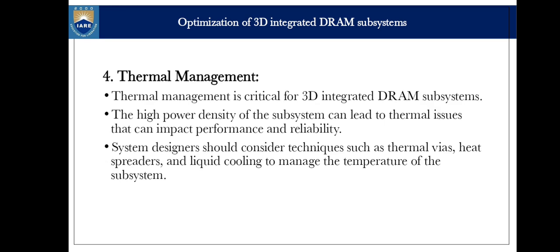Thermal management. Thermal management is critical for 3D integrated DRAM subsystems. The high power density of the subsystems can lead to thermal issues that can impact performance and reliability. Subsystem designers should consider techniques such as thermal vias, heat spreaders, and liquid cooling to manage the temperature of the subsystem.